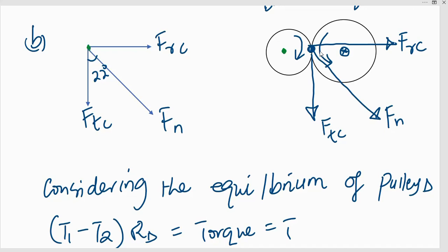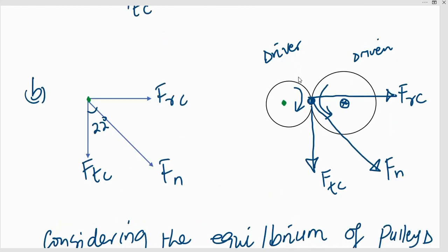Now if I also expound more, if this is a pinion which is a driver, the pinion is driving gear C, this is C which is driven. So if I consider a pinion rotating, that gives a vertical downward tangential force. If it rotates in a clockwise direction, then it means the driven gear C will rotate in an anti-clockwise direction. So the tangential force is going to be tangential to all the pitch circles of the two gears. This is the pinion, this is the gear that we are driving. Then this is mounted on a shaft whose dimensions are to be determined. Then the normal force will act, so it comes like this. So when it comes like this and this moves like this, then the normal force will act in that particular direction. Then the tangential force acts downwards and the radial force in the horizontal direction, and it will be perpendicular to the axis of the shaft.